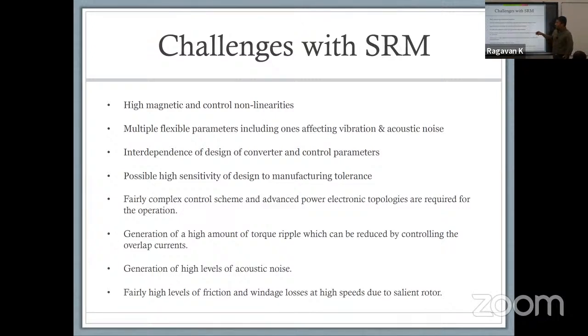So in terms of the control scheme, the scheme itself is not very complex. I think my language there is somewhat misleading even as I read it. It's not as much the control scheme being complex, it's more that the converter topology tends to be a little more involved, and in the control itself, you are just doing simple current control. You're doing hysteresis control, which is one way to do it.